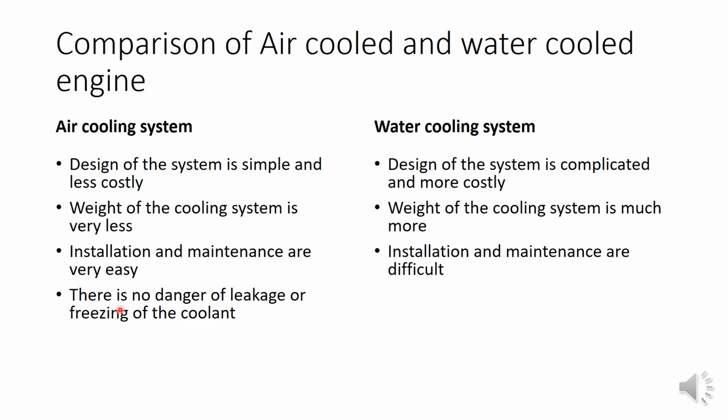And another point is there is no danger of leakage or freezing of the coolant in air cooling system. In air cooling system we are simply using air, so we don't have to care about the leakage or freezing problems, etc. But in water cooling or liquid cooling, there is a danger of leakage. So if somehow the cooling water is leaked, it will affect the performance, and freezing also very much adversely affects the performance of water cooling system.